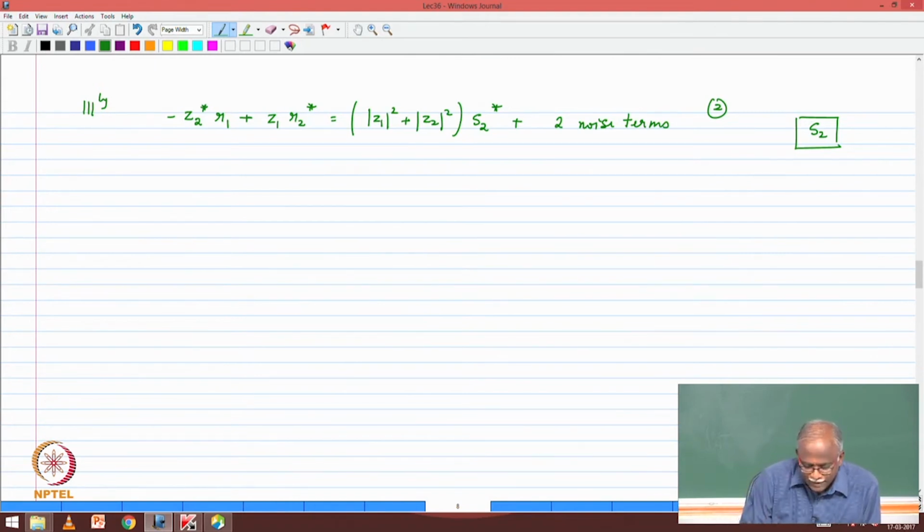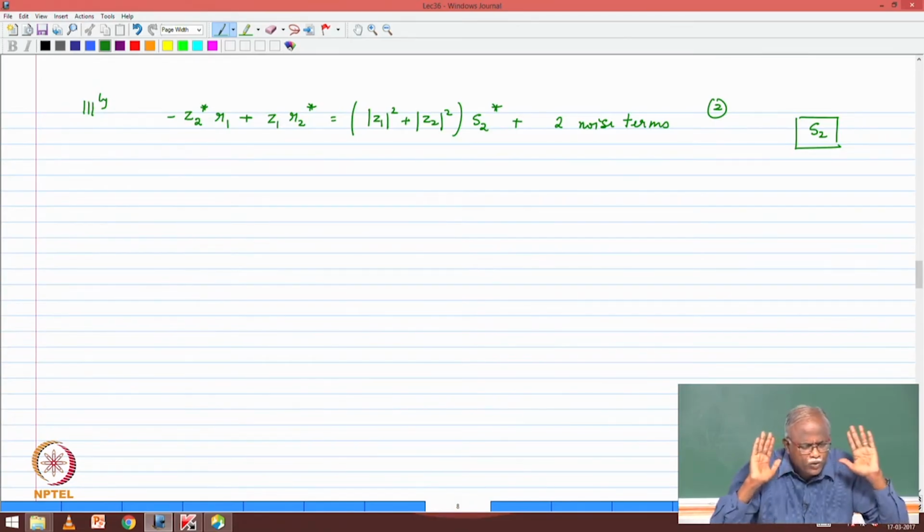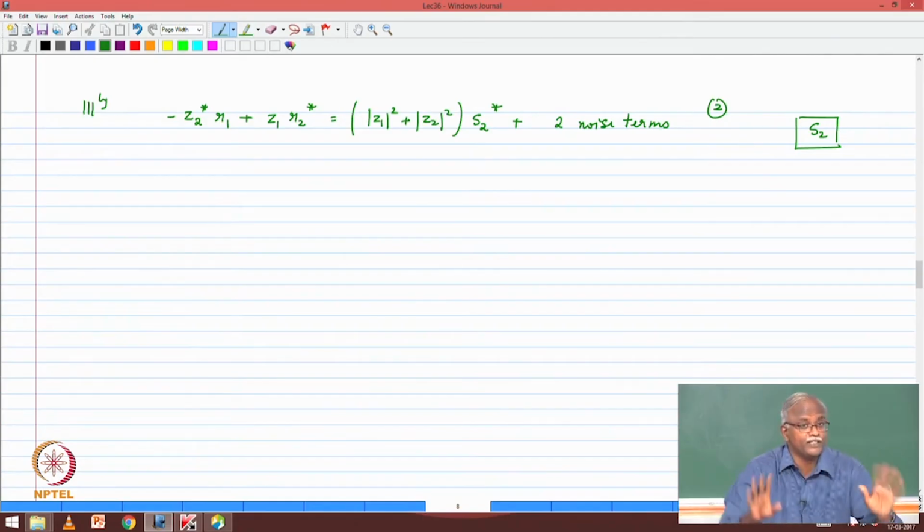So this is a very important result, because what it says is, typically we think of diversity as something you can get when you have multiple antennas at the receiver. What this technique said was, no, that's not necessary. You can actually transmit 2 signals on the transmit side. Traditionally, you would think, if I transmit 2 different signals on the same frequency, they will interfere with each other. I'll have a big mess at the receiver. But what this one says is, no, if you design your transmission carefully, then you actually get 2 branch diversity in this system. Okay? Everyone is very happy with this result.